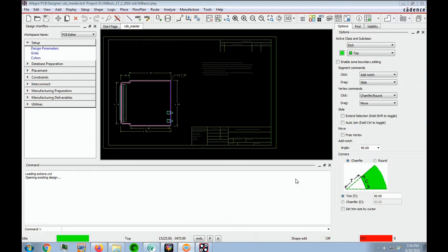In this lab, you create a PCB editor design.brd file. This design file will contain only mechanical data. No logical schematic data will be loaded. This design file serves as a master template or starting point for all layouts that require its mechanical specifications. This ensures that all physical layouts with common geometry start from a mechanical template that has been thoroughly checked and approved for use.